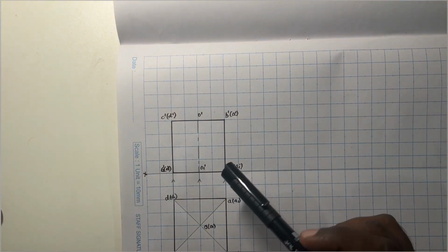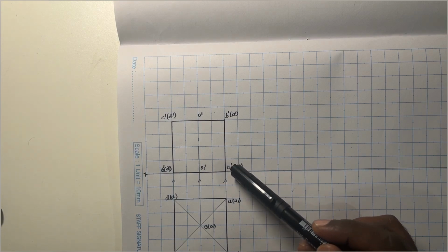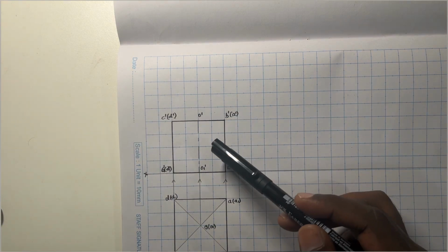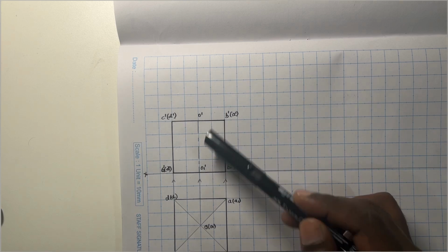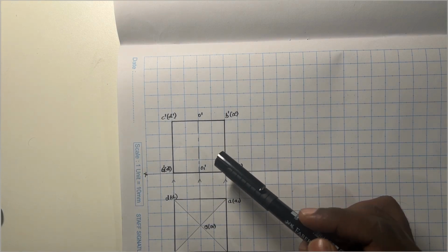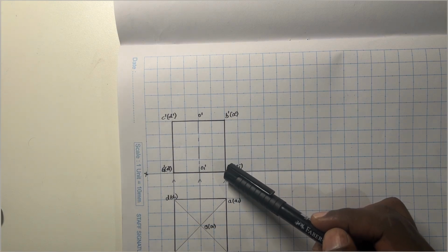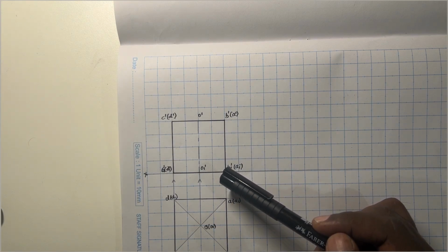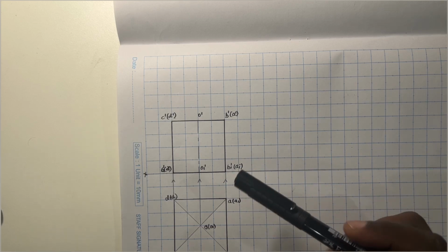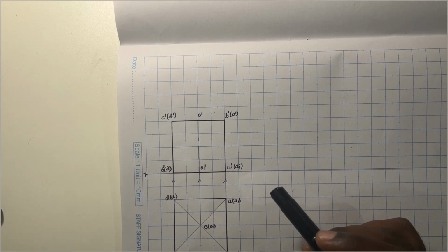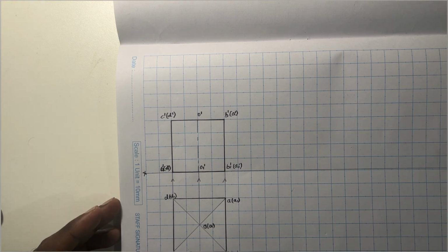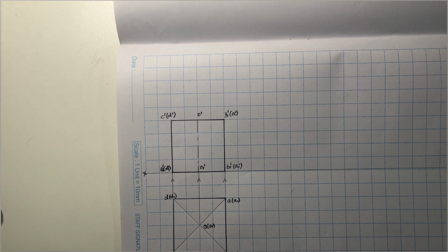You can just see that this edge in the front view, that is B1 dash A1 dash, and B dash A dash, and also O dash O1 dash, these are lines which are parallel. So if I'm making an inclination of the axis at 50 degrees, even this edge will also be inclined at an angle of 50 degrees because there will be the alternate interior angles. Now I'll construct the base inclination angle, which is equal to 90 minus the axis inclination, that is 50. Let me proceed towards the next step for constructing the base inclination angle.